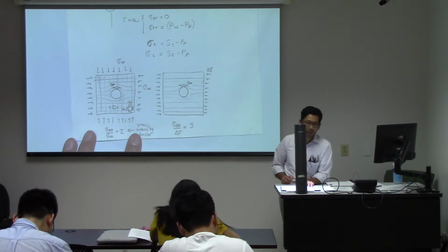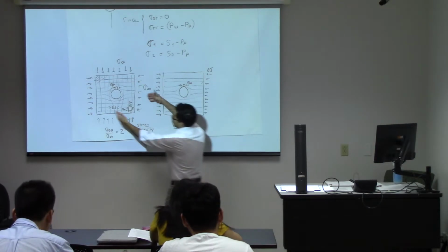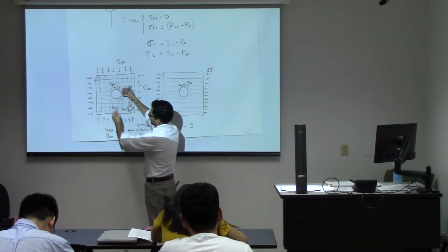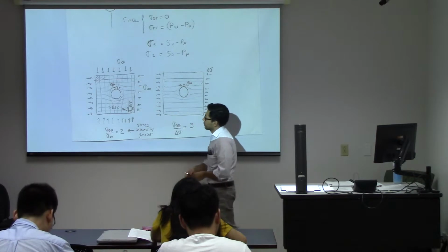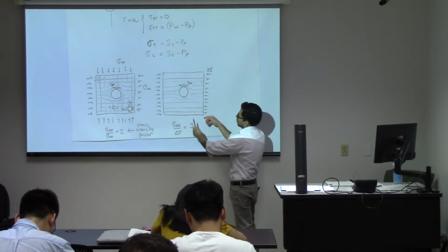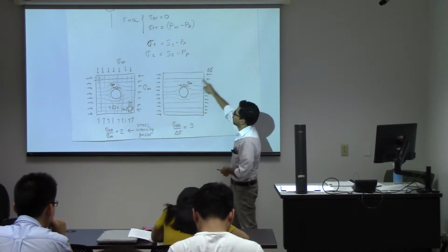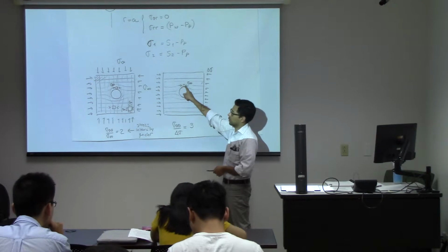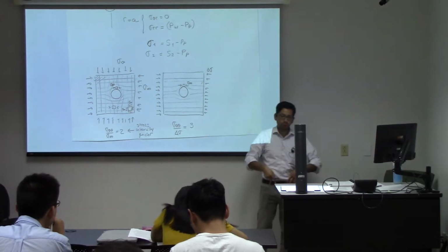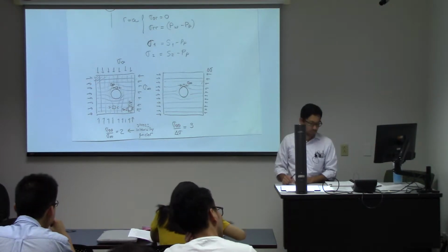So which means that if you had stress just in one direction, before we had in two directions, right? And that sort of compensates the stress in this direction. But if you had just stress in one direction, now we're going to have 3 times that amount at the face of the wellbore. So more stress anisotropy than before.